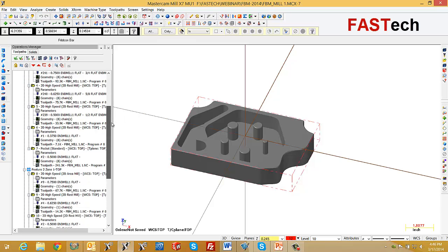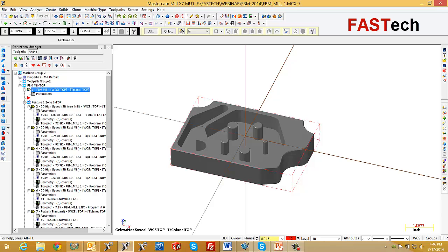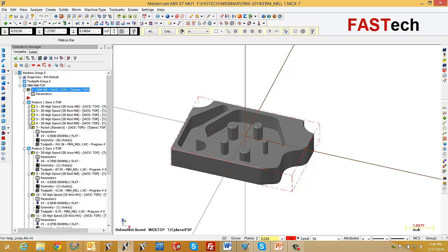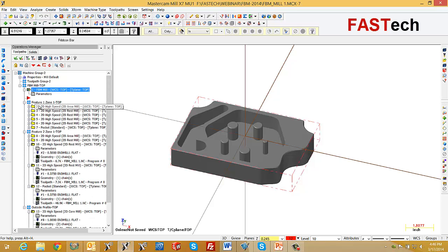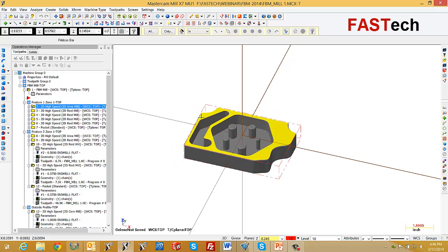Now we can see that I have quite a bit of toolpaths on here, and it's going to cut the part, but it's going to cut the way that Mastercam felt that it needed to. And right off the bat, if I do a machine type area, you'll notice it put a pretty big tool in there because I never told it what range to stay within. I just had Mastercam pick it. Now let's try a different solution on how this would work, much faster as well.